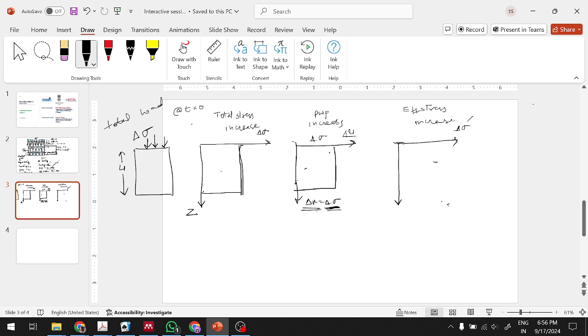Okay, but why throughout the depth will we have the same? You see, here throughout the depth we will have the same water pressure, because as the pores are interconnected, the load transfer mechanism, the water, like the whole phase, will bear the weight, not only the top surface or the bottom surface.